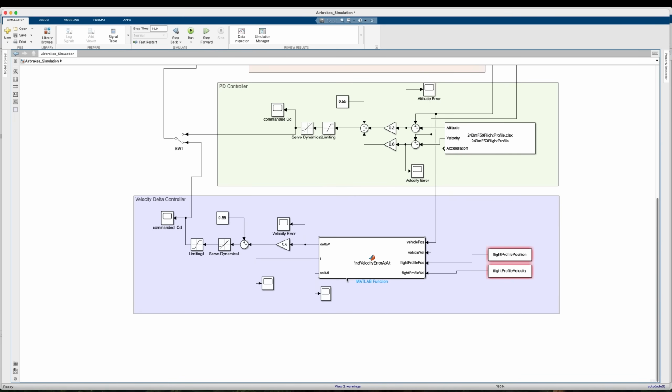How we're going to do that is we will be comparing our rocket in simulation, and hopefully in real life, position and velocity to the position and velocity of that reference trajectory. If we are higher than we should be based on our reference trajectory, we'll deploy our Airbrakes more. And if we're lower than we should be based on our reference trajectory, we'll pull our Airbrakes in. There's a couple different ways to do that.